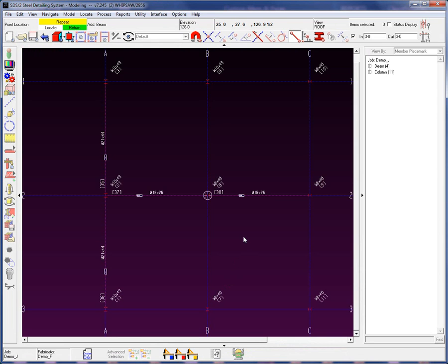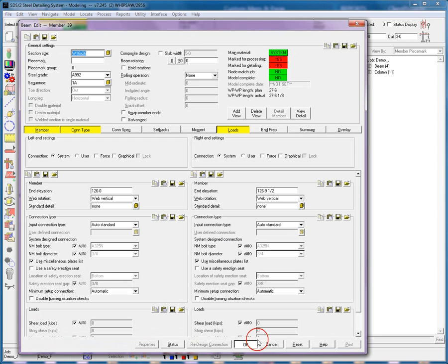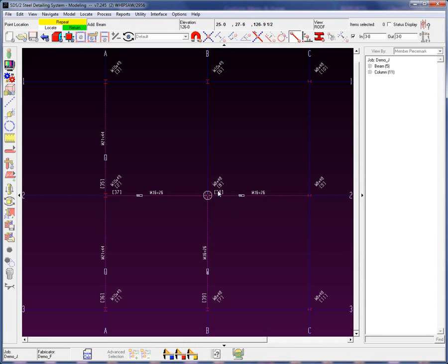Now let's go ahead and add in some sloping beams right here. Again, I'm going to use my exact point. Doesn't matter, the top of column's at 126.0. I'm going to put in the first point, second point, that's good. This happens to be a 16 by 26. I can't repeat it here because I'm sloping from grid line 2 down to grid line 1, but I can repeat this member here, so I'm going to repeat, repeat, repeat, and that will complete adding in these sloping members right here.